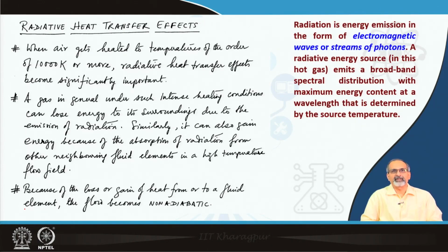Radiative heat transfer effects. When do they become significant? That is the first question we would be interested to answer. So, when air gets heated to a very significantly high temperature of the order of about 10,000 Kelvin or more, radiative heat transfer effects become significantly important. The gas in general under such intense heating conditions can lose energy to its surroundings due to emission of radiation. Similarly, it can also gain energy because of the absorption of radiation from other neighboring fluid elements in a high temperature flow field.